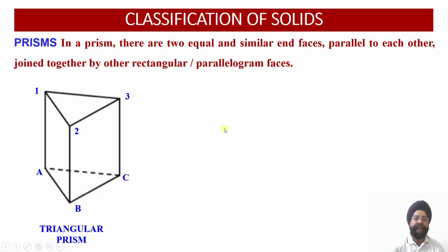Now the second thing which is required in any given prism or any given pyramid is to evaluate and locate the axis of the solid, because in solids two things will be given. The edge of the base will be provided, that is, if it is a rectangle, then the length and breadth of the rectangle will be provided. If it is a triangle, let us say an equilateral triangle, then the edge of the base will be the edge of the triangle. So one edge of the base will be provided and the axis height will be provided in any given prism or a pyramid. So only two things are required, and you are required to carry out the construction of the front view and the top view of the solid.